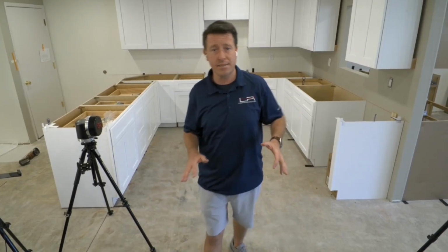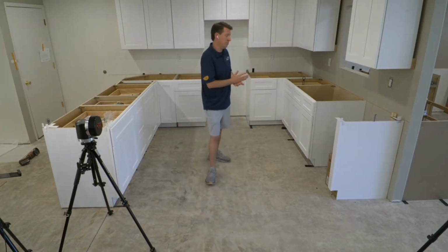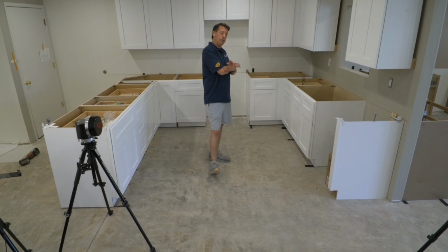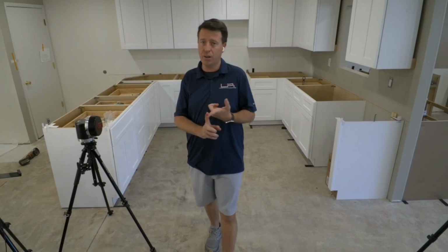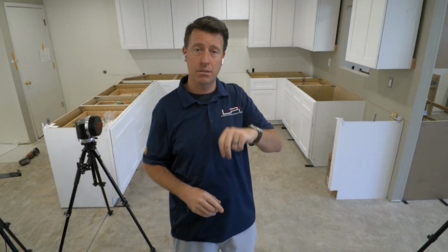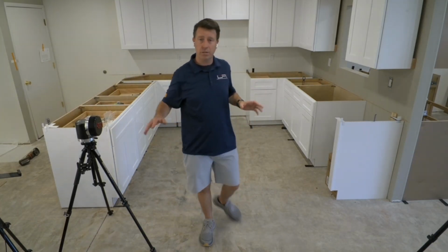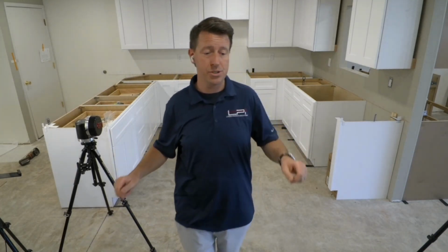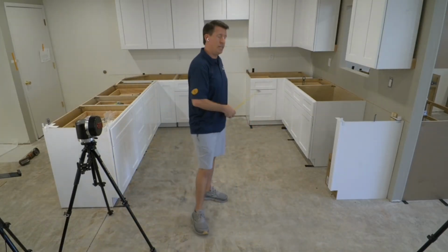So the core, the basics, just to kind of review, we want to have proper setup. I talked about this a few times, but it's essential to finding those best habits. Prep your area by clearing everything off and setting your targets. Find the laser position, set a proper plane. You'll capture your area, connect your corners, and then check your dimensions. Right? Close all your corners and check the raw dimensions.